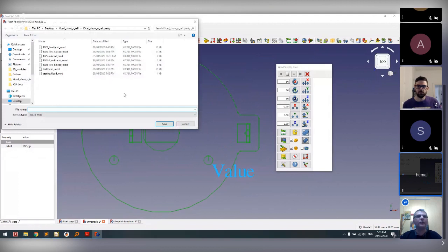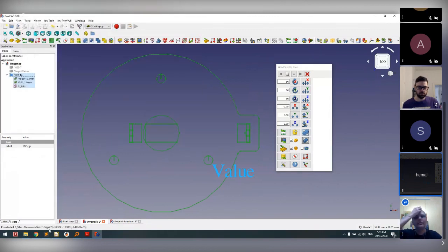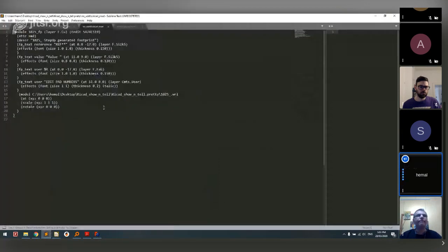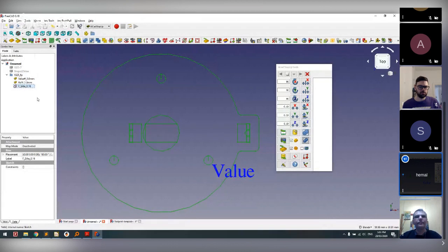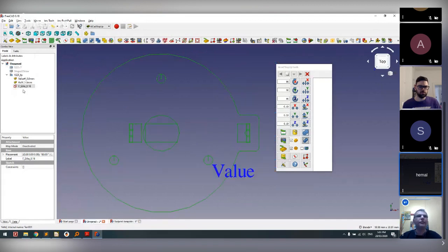Let's see. Okay, so let's open. So no, it didn't. So I think it's a script which expects that thing to be there. So those names are hard baked into the script. We have to use those. That's why they have provided this footprint demo template. You have to use this template to name things. Yeah, that makes sense.